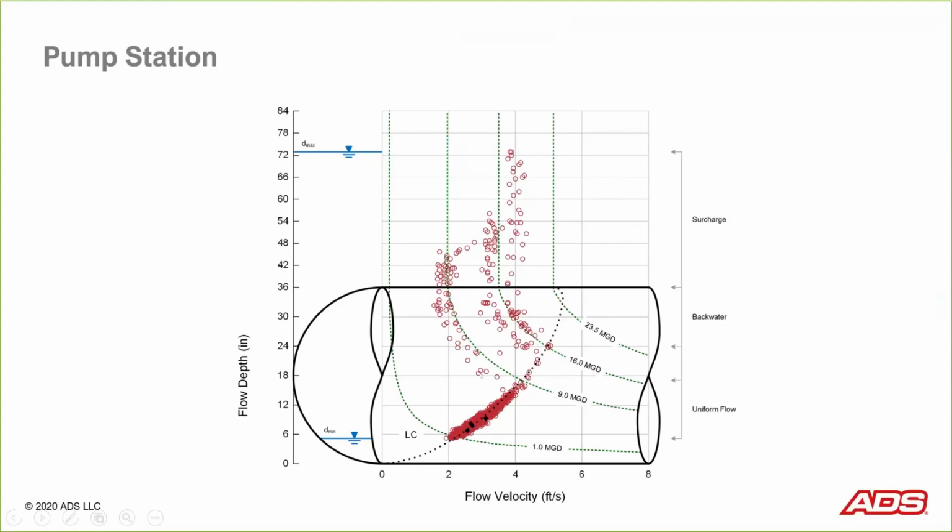And so some of the interesting things we discovered from this particular one is obviously most pump stations have a lead pump that alternates between two different pumps. So one pump operates as the lead pump for a while. Later on, maybe the next day, the next pump operates as the lead pump. Various ways of doing that.